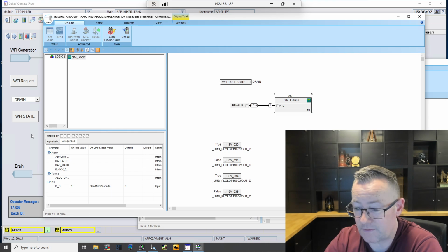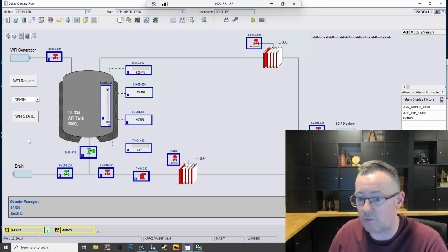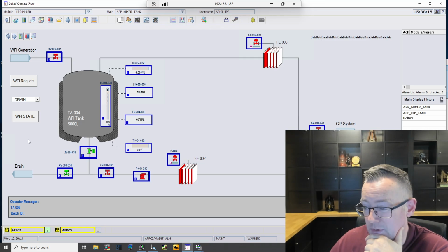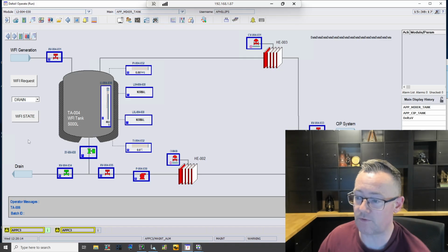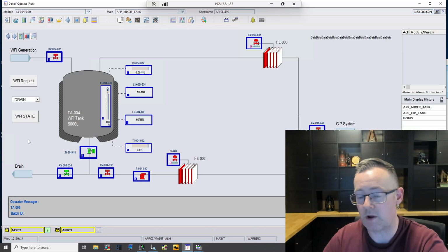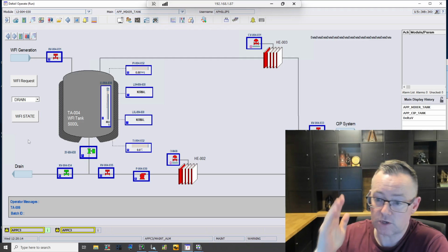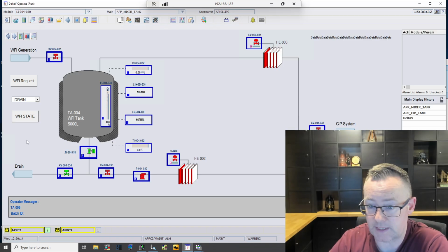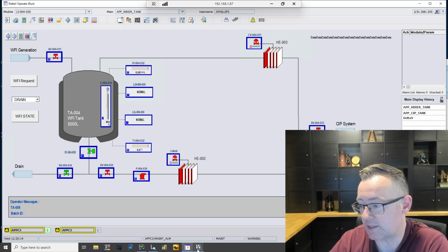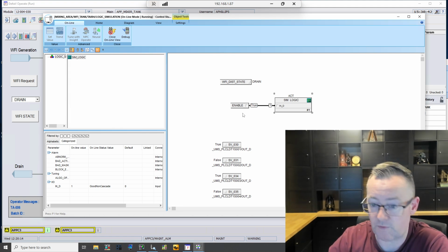So essentially the action valve is very much if statements. You can do a kind of loop in there as well to a degree, but that's what it's used for. It's done for a lot of, in my opinion, quick logic in a system before you get into the proper sequential function chart logic. It's also done for some form of calculations. You trigger the enable, and he does his thing, and then when you want him to stop doing whatever calculation is inside, you kill the enable on the outside until you want to perform that calculation again.